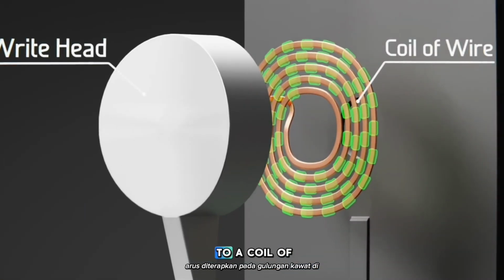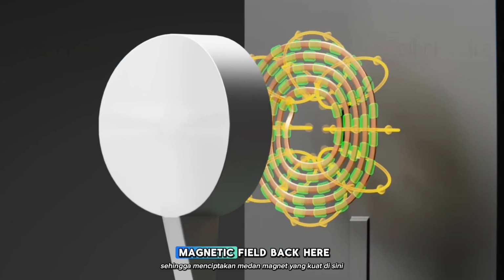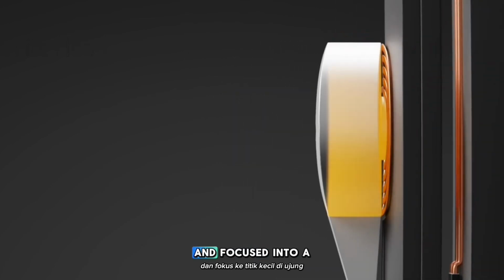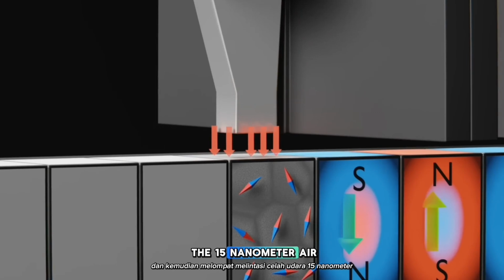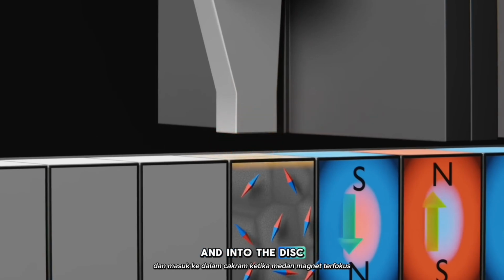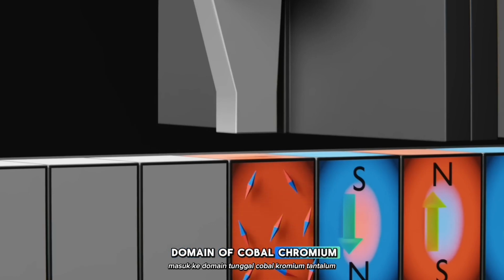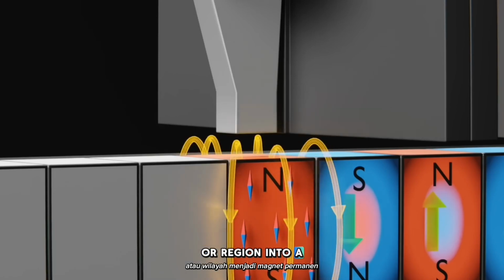A current is applied to a coil of wire at the back of the write head, thus creating a strong magnetic field back here. The magnetic field is channeled through the write head and focused into a small point at the tip, and then jumps across the 15 nanometer air gap and into the disk. When the focused magnetic field passes into a single domain of cobalt chromium tantalum, all these atoms are forced to align their tiny atomic magnetic fields with the applied magnetic field from the write head, thus turning the small domain or region into a permanent magnet.